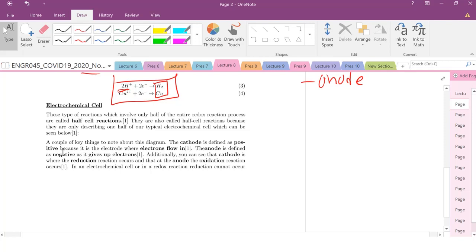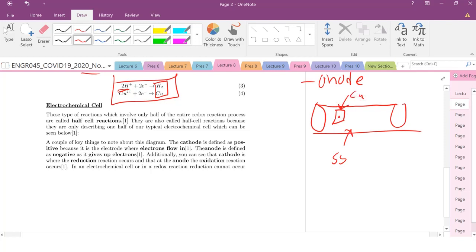So one way we could test, and again, this is important, right? If you have a pipeline, usually you have some pipe made of some material, let's say stainless steel, but you might have some bracket on here, my poor drawing skills. This bracket might be made of maybe pure iron, who knows, maybe copper, just throwing an example there. You'll have corrosion there. If those 2 dissimilar metals are in contact, there's going to be corrosion. So we need to figure out what material is going to corrode, how fast it's going to corrode, and when will catastrophic failure occur.